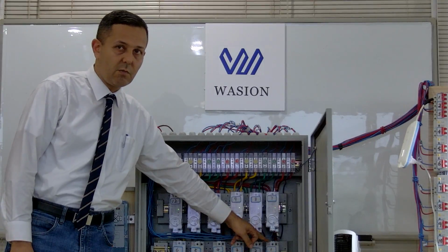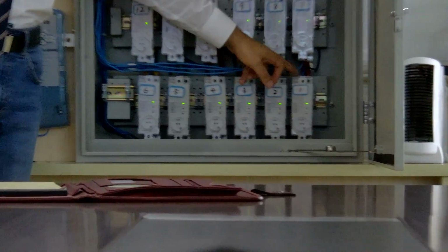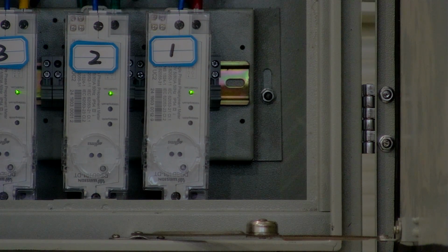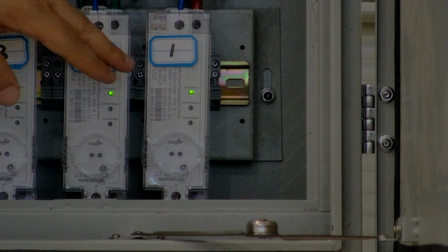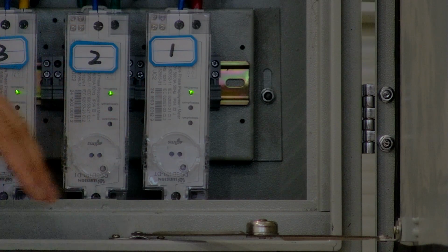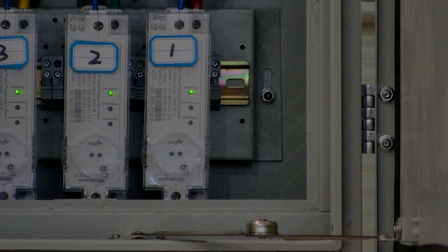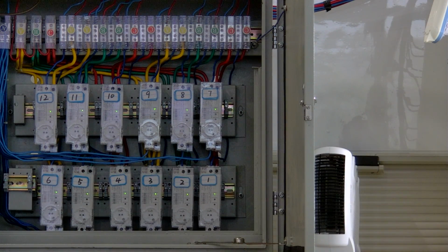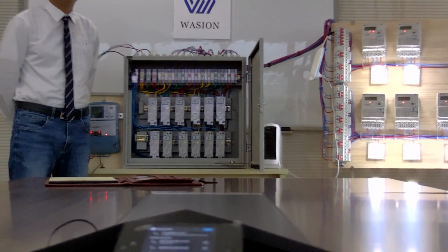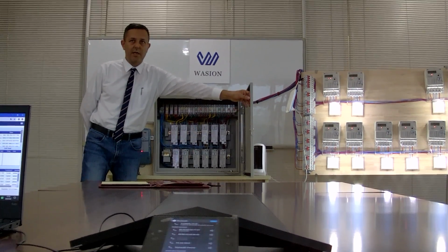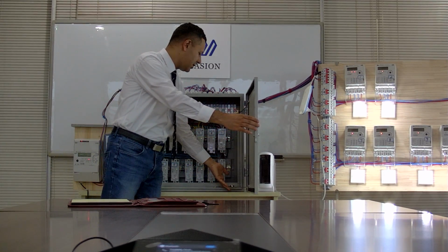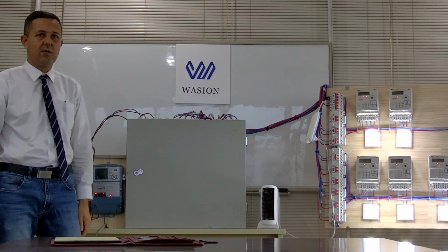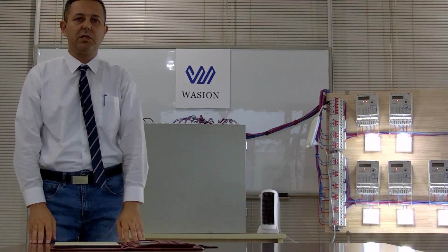This is check meter number 1, which is the replica or the relative meter for meter number 1 in the premises of the customer. So this meter will detect and measure the consumption of the heater, which is the illegal load illegally connected to the grid, and then will send the command to the head-end system, which is located in utility premises, in headquarters, and then the headquarters MDM system will send this disconnect command to meter number 1.